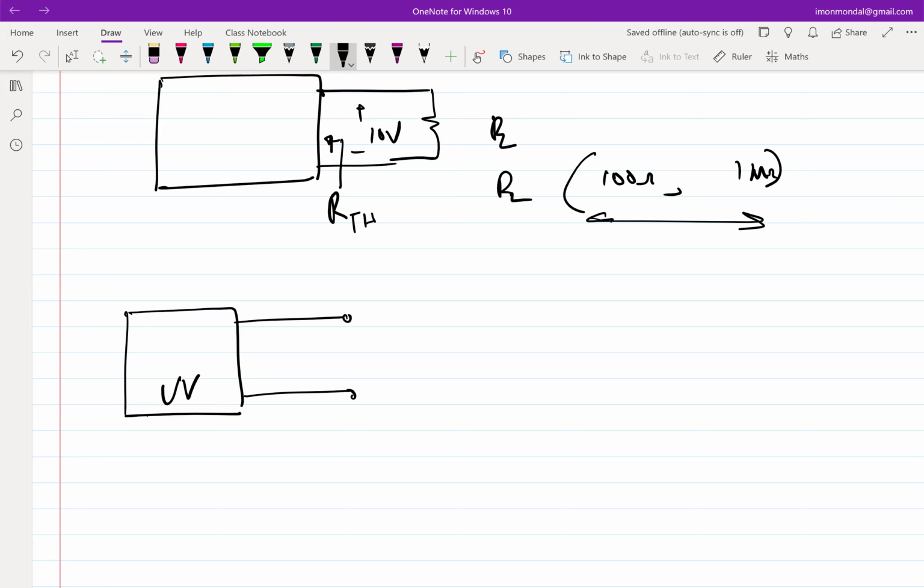Short and open the sources. Fine. So I have sources, correct? So I short the voltage source. If I have a current source, I open the current source. So then what next? Good, add a temporary source. Great. Voltage source or a current source? Anything, doesn't matter. Let me add a voltage source. I call it V test. This is a test source we are adding because this is not a part of the circuit, so we are adding it explicitly for some purpose. We added a V test.